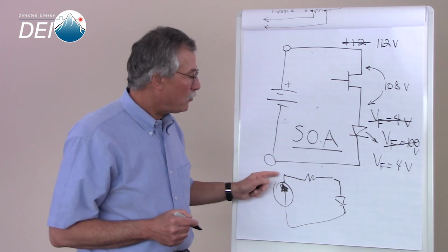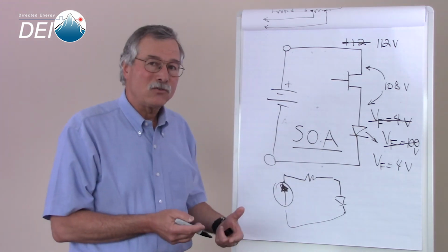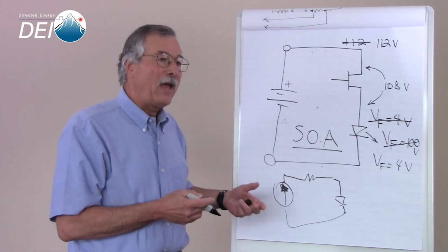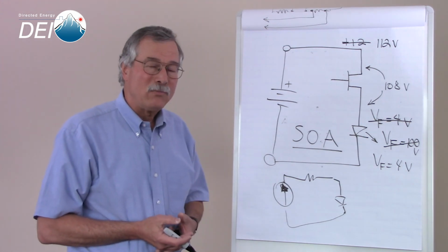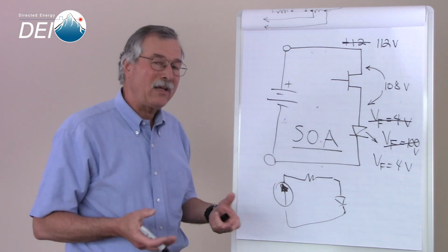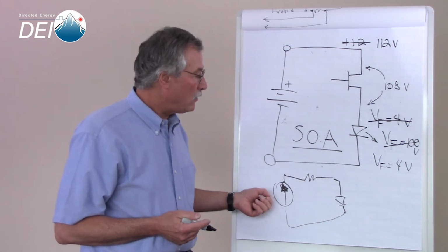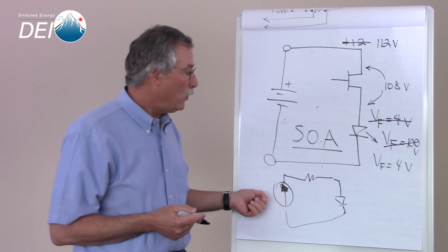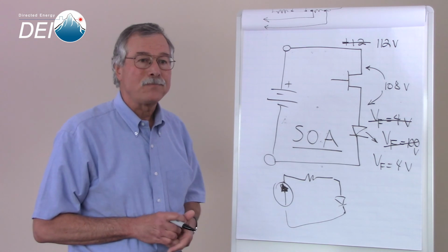So the purpose of the strip line cable, the heavy duty cable, is to get the most amount of current transferred from the source to the load in the least amount of time and with the least amount of losses. That cable will get warm if there's a large amount of current flowing through it, so we make it thick and wide. We also want to keep the inductance down, and consequently we use techniques that may look like impedance matching, but the fact is we are not. It's strictly a maximum current sort of operation.